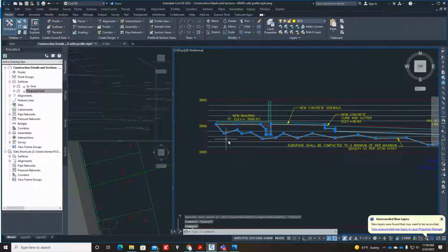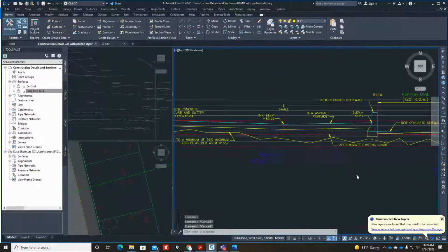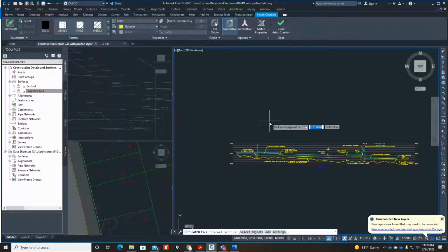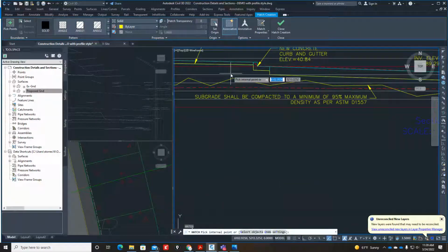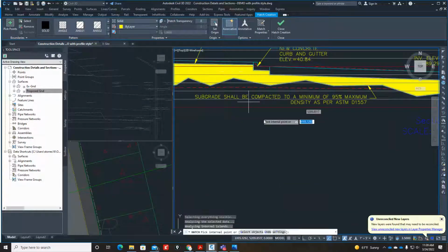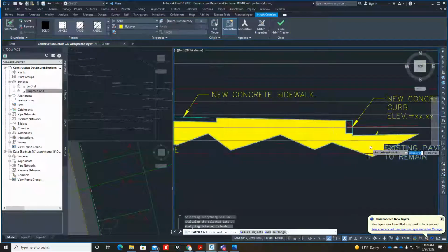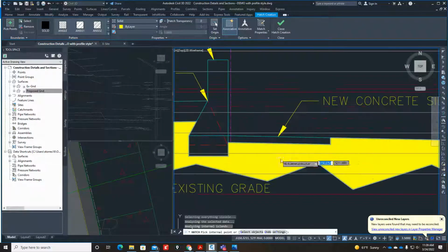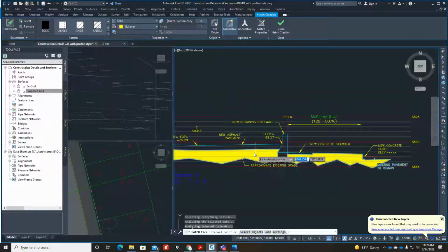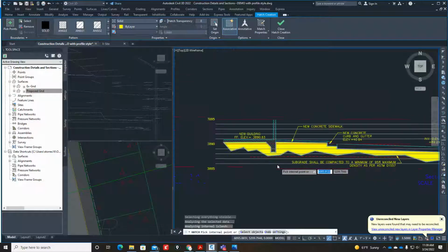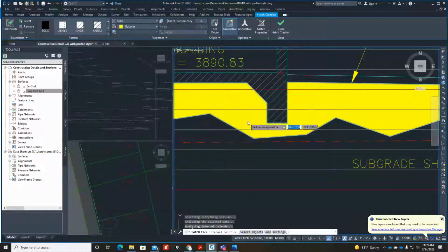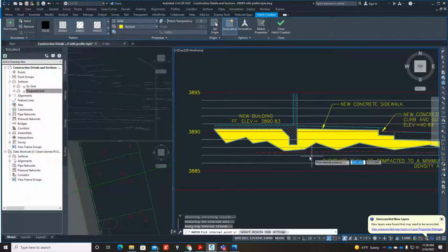Okay. That's the shape I'm going to use. Now, as far as a hatch pattern, we're kind of used to doing this type of thing. But the thing is that, okay, well, it found that area real nicely, but sometimes it uses the grid lines as a boundary, so it won't let you hatch. You'll have to pick a little area here and one here and one here and one here, but this one worked out real nicely.